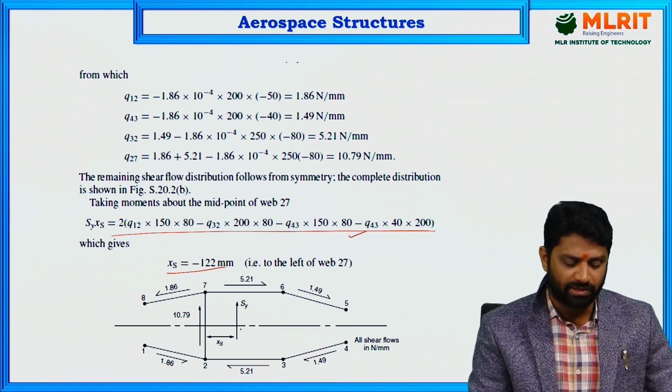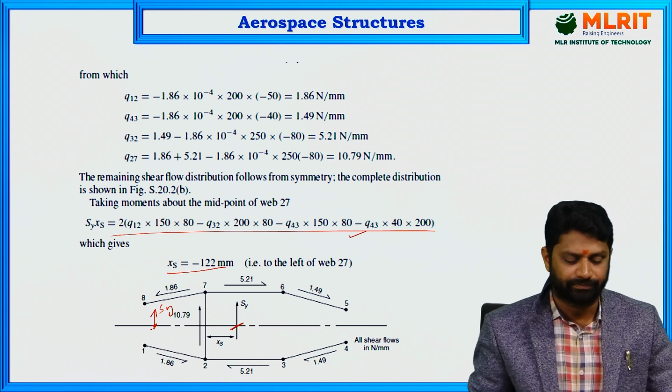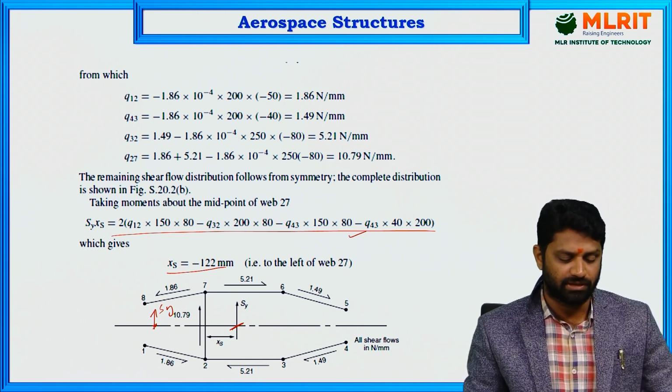That means we assumed the shear center here, but usually the shear center acts on the left side, like this. That is how we calculate the shear flow distributions.